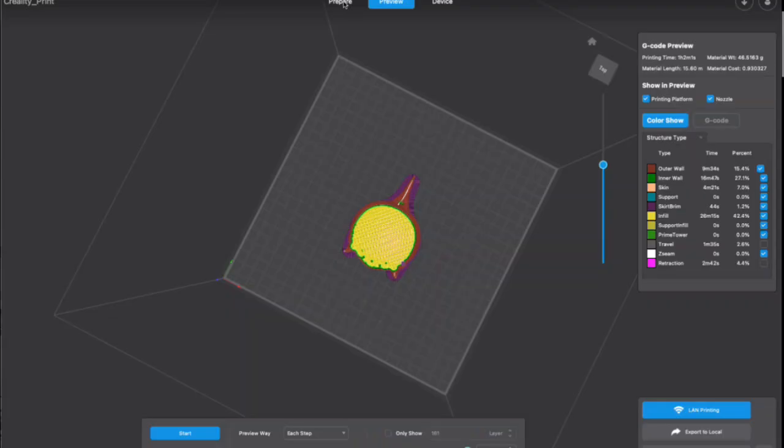If I don't like the object in FDM, you can do that, not in resin. In FDM, you can shred the part, as FDM uses thermoplastic. If you shred the part, it will convert into small pieces. You can melt those shredded pieces, draw filament out of it, and use that filament again.